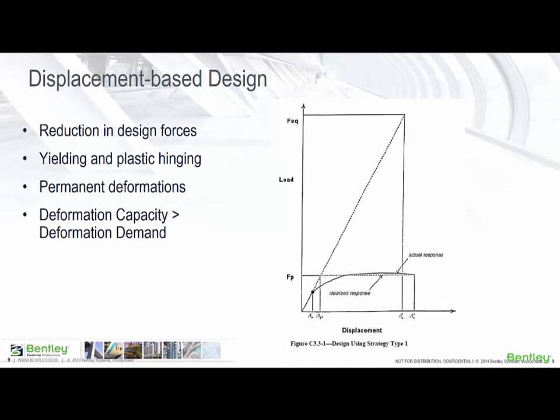Displacement-based design. In recent years, there has been a trend away from force-based procedures to those that are displacement-based, wherein a bridge is designed to have an adequate displacement capacity to accommodate earthquake demands. Displacement-based procedures are believed to more reliably identify the limit states that cause damage leading to collapse, and in some cases produce more efficient design against collapse.